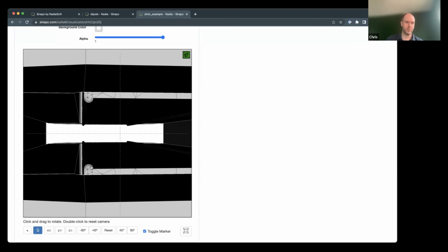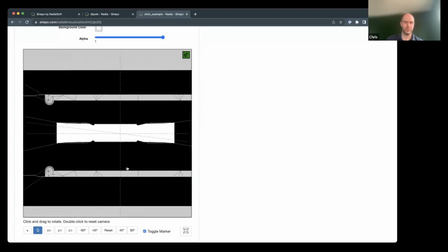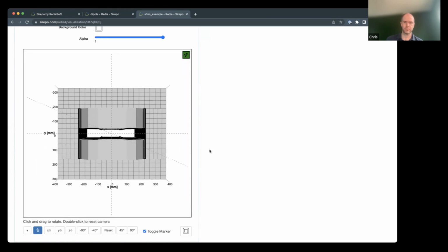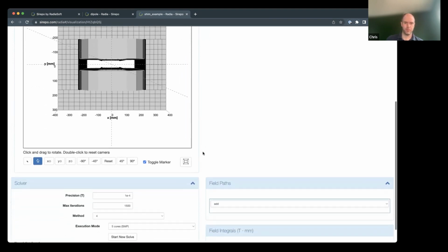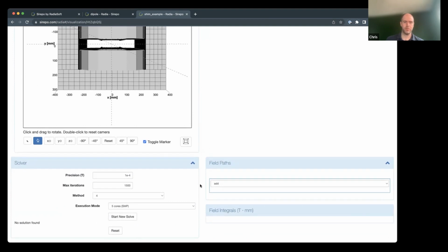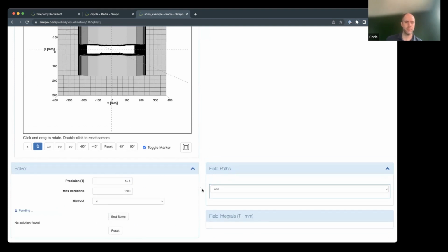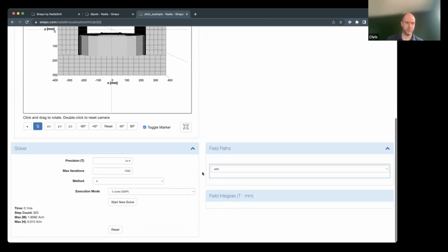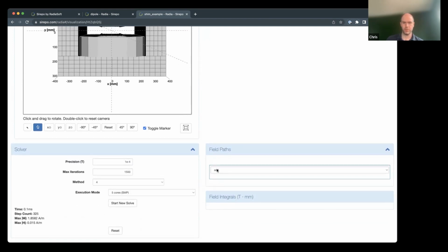Here we've got this rapidly changing semicircle and then a lot more coarse out across the flat regions of the magnet. And we'll try real quick here. I'm running this. This might take another second or two since there is a lot of additional segmentation now in that pole face, but it's still pretty quick to run.